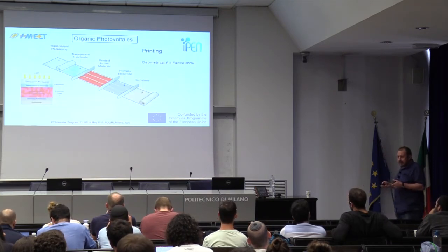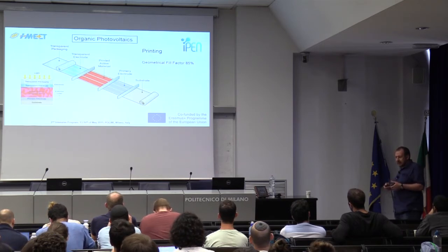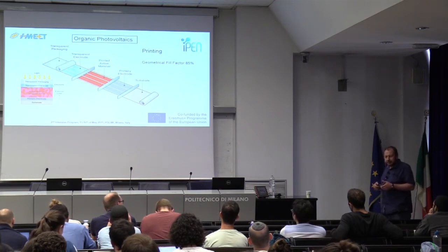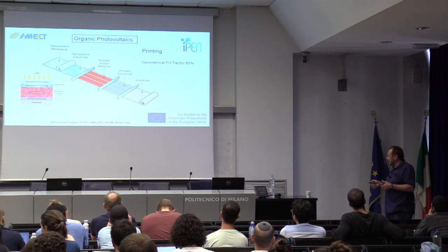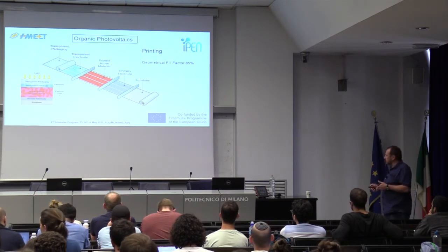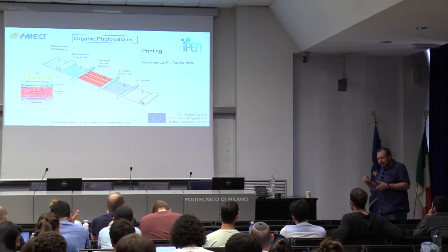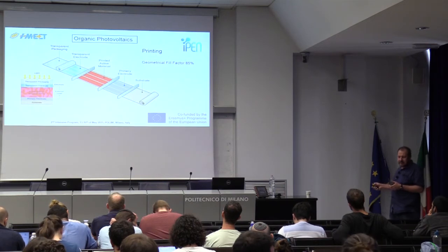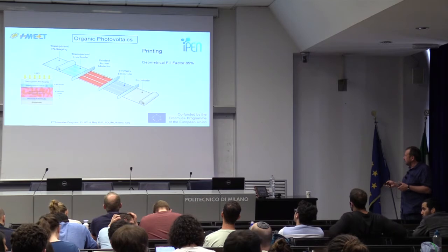How can this be done? One of the main advantages of organic photovoltaics is that it is solution processable. So, if it is solution processable, it is printable, and it can be applied also to roll-to-roll production. And this way you can print the cells in these ribbons and do the structuring. But the area losses tend to be very large in this case. The geometrical fill factor is not very high. So what can be done?